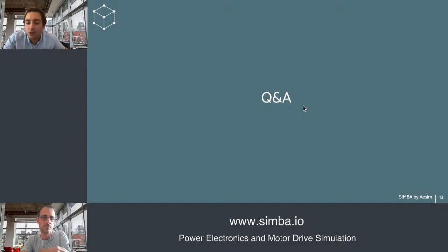Thank you. Another question from Eren. What about reverse recovery effect of diodes? Is there any plan to implement a reverse recovery model for diodes? So 2 things here. We can actually simulate already the thermal losses from the reverse recovery using the thermal model that we have implemented. But it's not possible yet to see the waveforms, to simulate the waveforms. This will be available in I think 2 or 3 months, somewhere in September or October, when we'll have more detailed diode and transistor models.